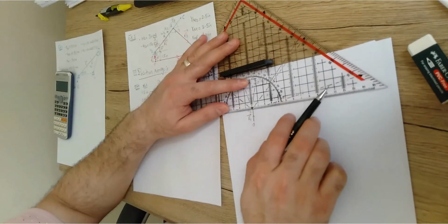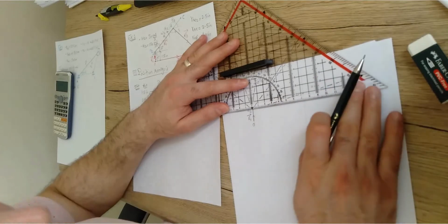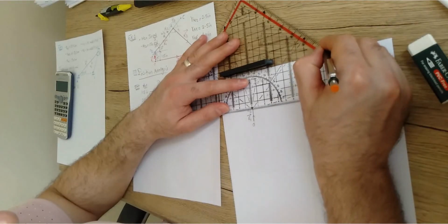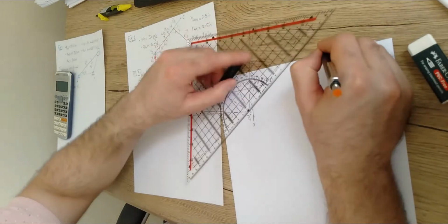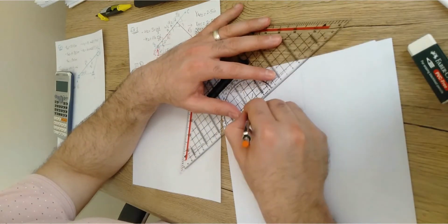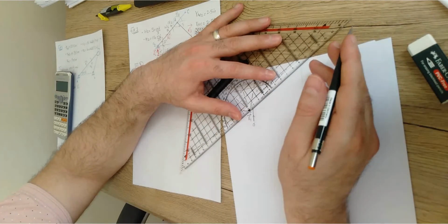Then I'm gonna measure 30 degrees in this direction. So this 30 degrees will be 10, 20, and 30, and mark a point. Even if it is over the disk, don't move the drawing sheet, and connect this point to this point to end up with the line. So we measure the angle, then we draw a light line.